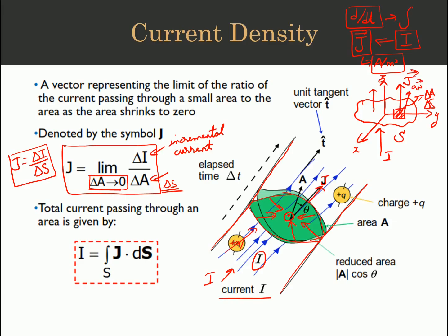So I can say that my incremental surface current density could be represented as J normal equal to the ratio of delta I by delta S, or I can say that delta I is equal to the normal current density times the surface, and we already know that the effect from the surface is always normal, represented as the unit vector normal. Similarly, if I further elaborate this normality into its components, I can write delta I as J of n along the normal vector dot product S of n along the normal vector.